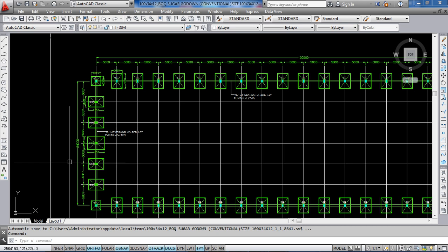By the truss height, we mean the height of the peak of the truss from the bottom chord. So center to center spacing of truss, then height of truss, and then another very important point is the spacing of purlin on the top chord.